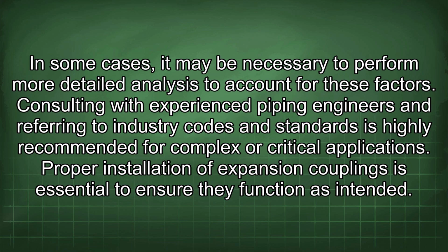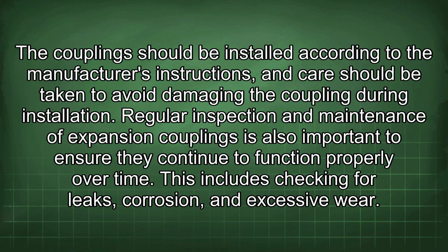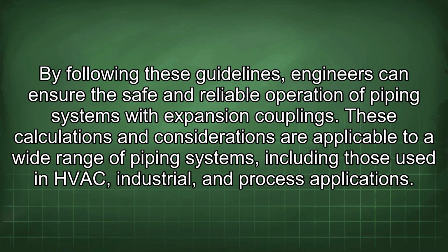Proper installation of expansion couplings is essential to ensure they function as intended. The couplings should be installed according to the manufacturer's instructions, and care should be taken to avoid damaging the coupling during installation. Regular inspection and maintenance of expansion couplings is also important to ensure they continue to function properly over time. This includes checking for leaks, corrosion, and excessive wear. By following these guidelines, engineers can ensure the safe and reliable operation of piping systems with expansion couplings.